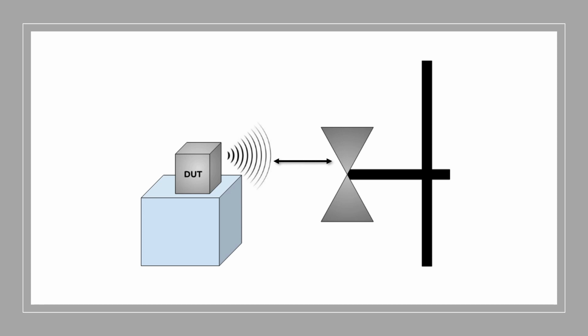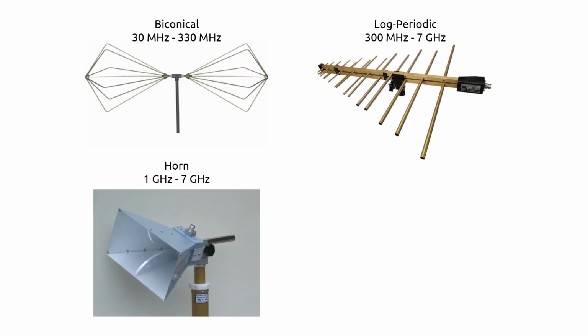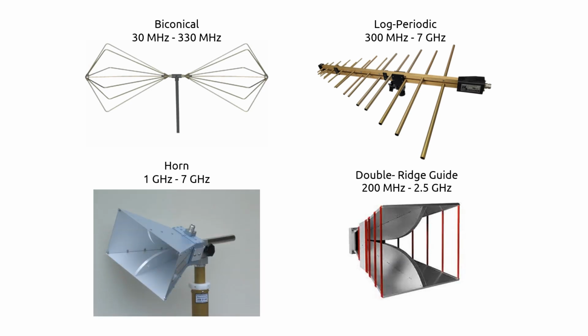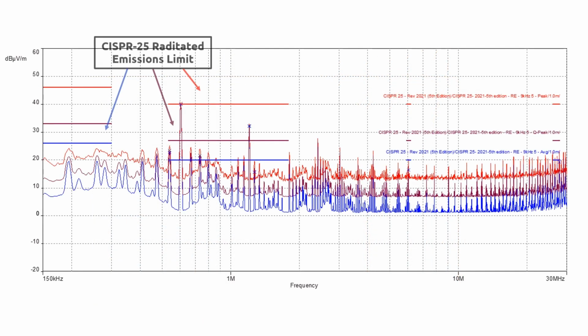An EMC antenna is a specialized type of antenna used to measure electromagnetic fields and radiation from electronic devices or systems. The design contains very little metal so as not to introduce or reflect significant electromagnetic noise off the device under test, which may interfere with the test measurements.